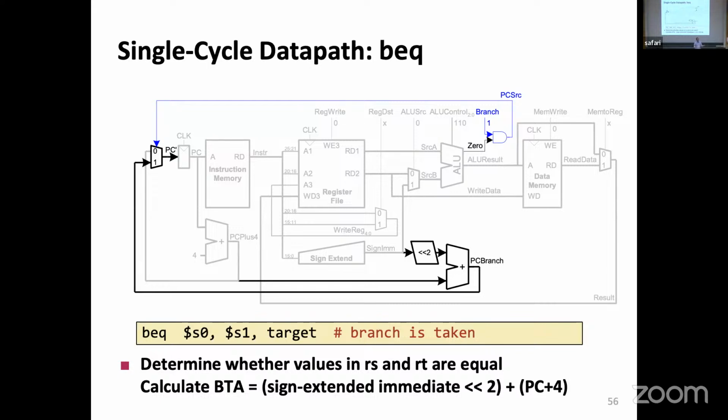That was a simple operation, could be easily added to the ALU, so that it can generate a special signal: the result of the previous operation was a 0. If the result of a previous operation was 0, and I am branching, this means that we should select the other one, the branch target address, as my next location where I'm getting my instruction from.